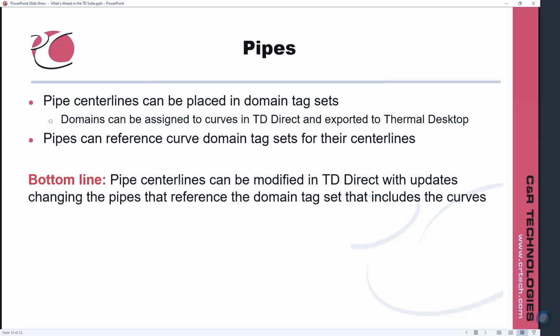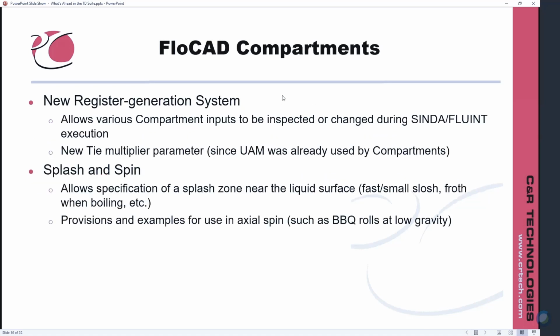We do have, and I recently, or no, I don't think I've posted the video yet, but I recently worked on a video that actually shows ways for edge contactors to make sure that you get the right edges. And there are ways to, if you right click in the field for the from objects, for finite elements, you can ask to pick only the free edges of the group of elements that you picked. So then it excludes anything that's an internal edge and only picks the edges that are exposed.